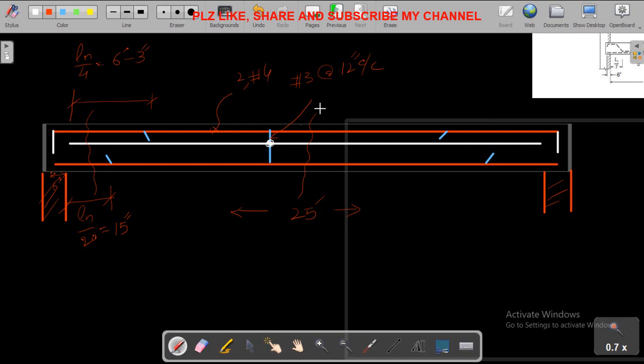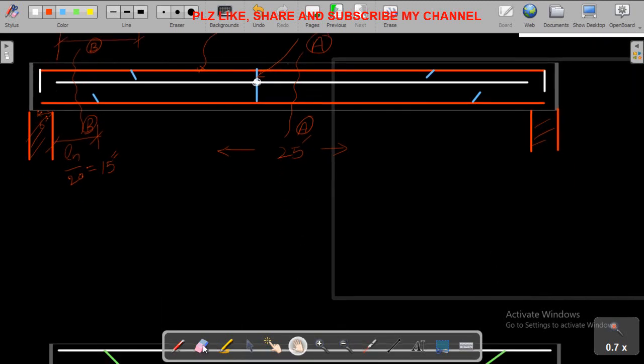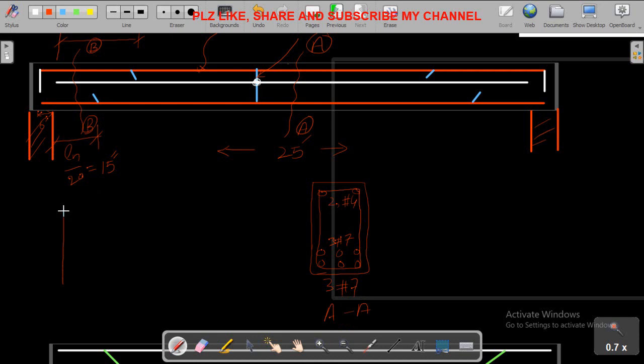Now here if we draw a cross section right in this AA, and if we draw a cross section right here BB, so at AA the cross section will be different. Here the cross section is 3 number 7 bar in the top and 3 number 7 bar in bottom, right? And here we can see 2 number 4 bar. This is section AA, but here the section will be different.